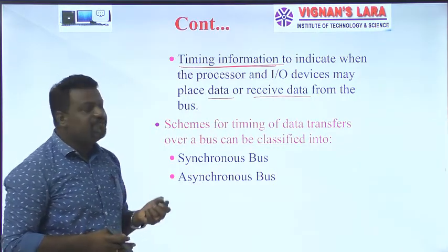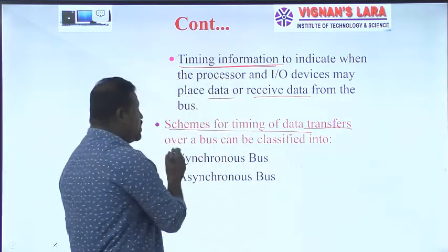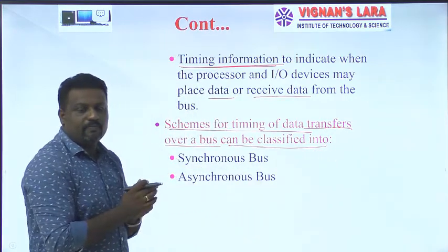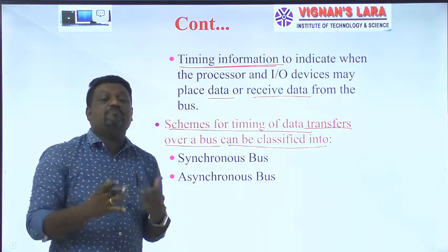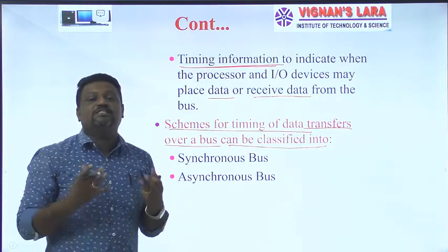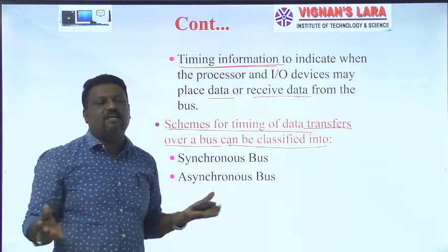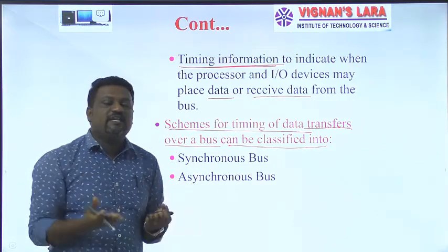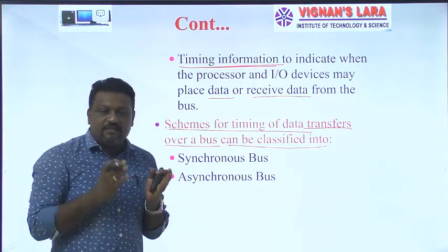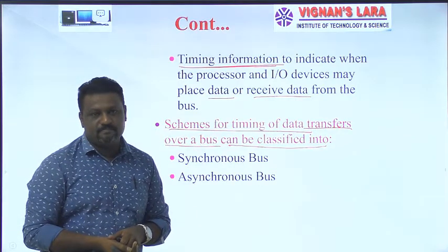And next, there are different schemes for timing of data transfers over the bus. That means here we are talking about bus protocols. We know that a bus protocol is nothing but a set of rules assigned to the devices which are connected to the bus: at what instant a device can go and place data on the bus, as well as at what time instant the device can activate or assert the control signals.